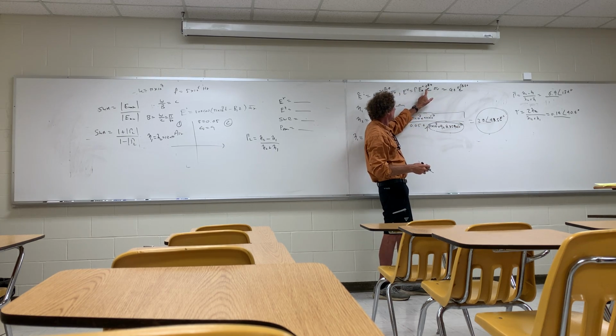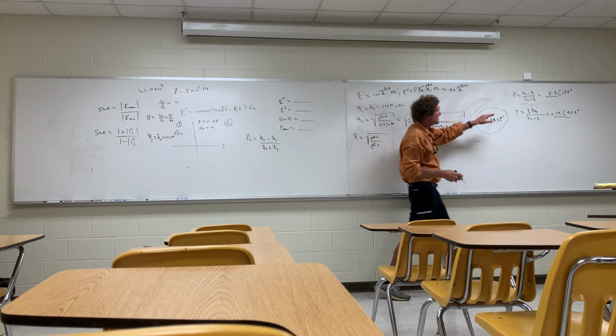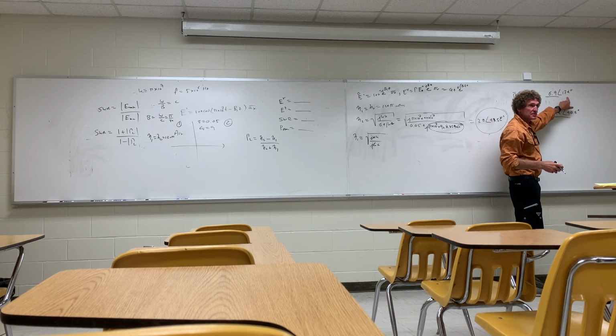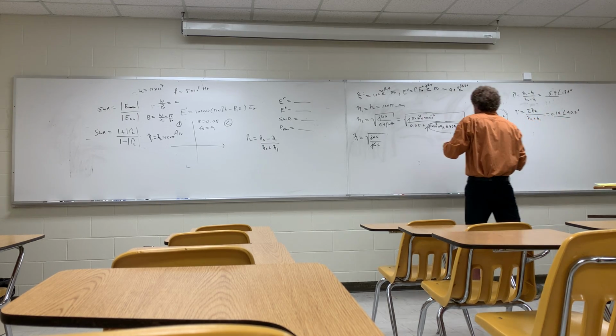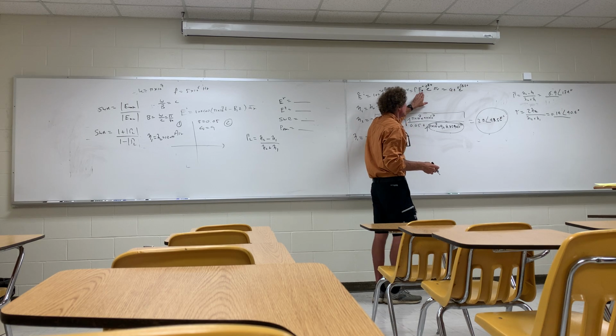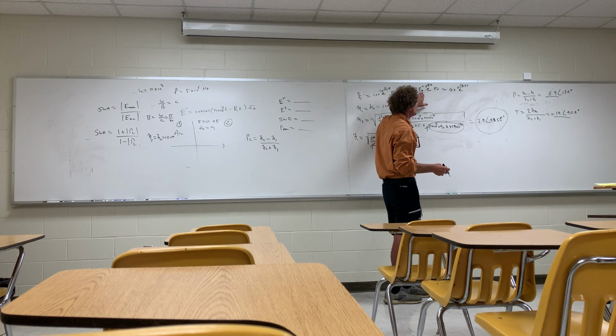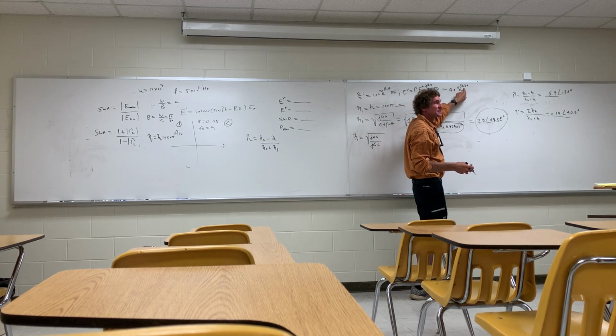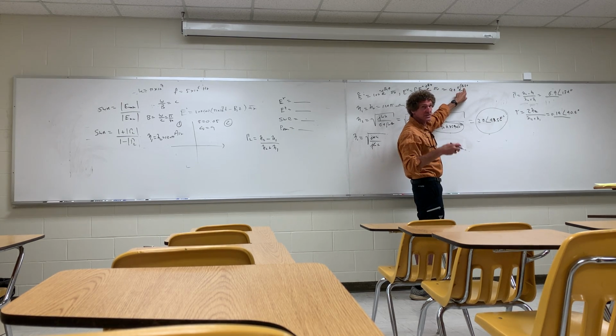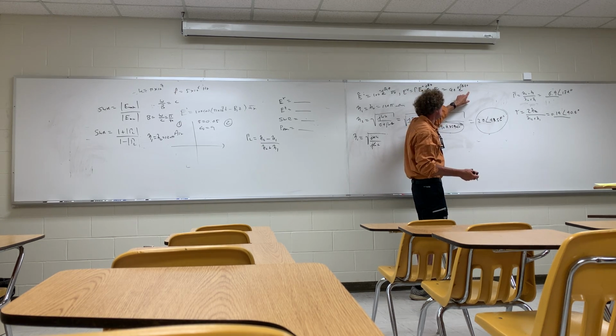You see how I have the reflection coefficient in degrees, right? Can you all see that? When I multiply the reflection coefficient times E, now you get a magnitude and an angle in degrees, but you see beta and z here are in radians. Do y'all follow me? All right, beta is in radians per meter, z is meters, so you get radians. So you should take the 174 degrees and put it in terms of radians when you put it in this argument. Do y'all follow me?